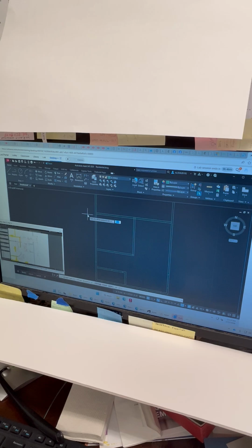And I forgot to mention, after we offset 2'1", we're going to offset 3.5 inches. So once again, I think 3.5 inches is going to be our go-to offset dimension because it's the one that's used most because of the thickness of the walls. All right, with that in mind, here we go again.